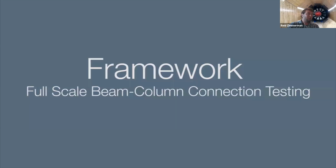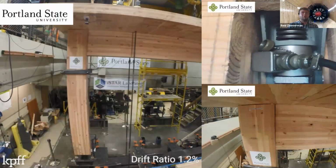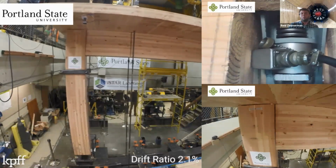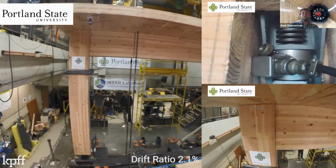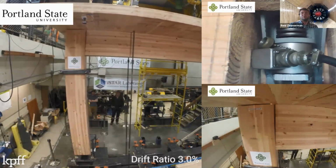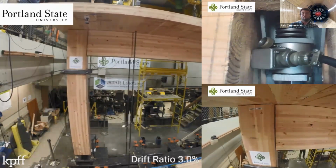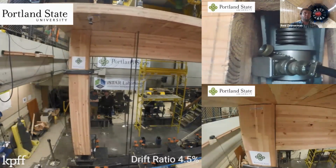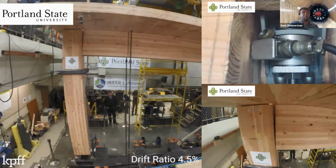So I'm going to show you a quick video here of what that looks like. This is going to be showing on the left panel the full view, a time-lapse view of the subassembly being worked. On the bottom right panel is a close-up of the joint. And in the top right panel, you can see essentially it's a spring that we've created using Belleville washers that keeps the beam from unseating. So as the gap forms, it then gets closed by this spring. And we went out to actually 6% story drift with this, with no loss of capacity and pretty much almost no damage.